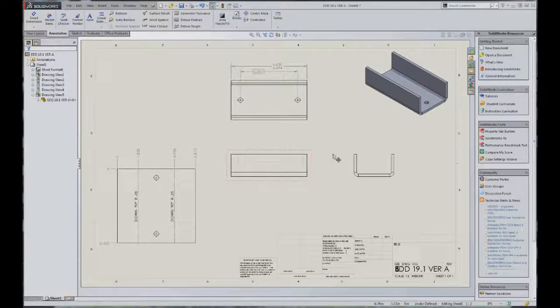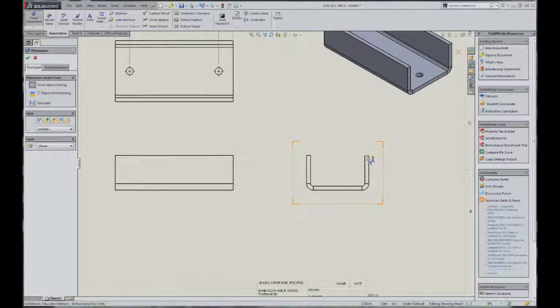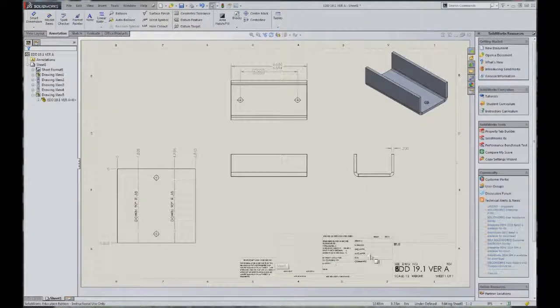Okay, and then somewhere in here, you're going to have to put the thickness, or you can put it in the materials. All right, so the material is called out as 5086-H32. That should be here in the material. Finish, I see no finish required, so there is nothing that you need to do there.